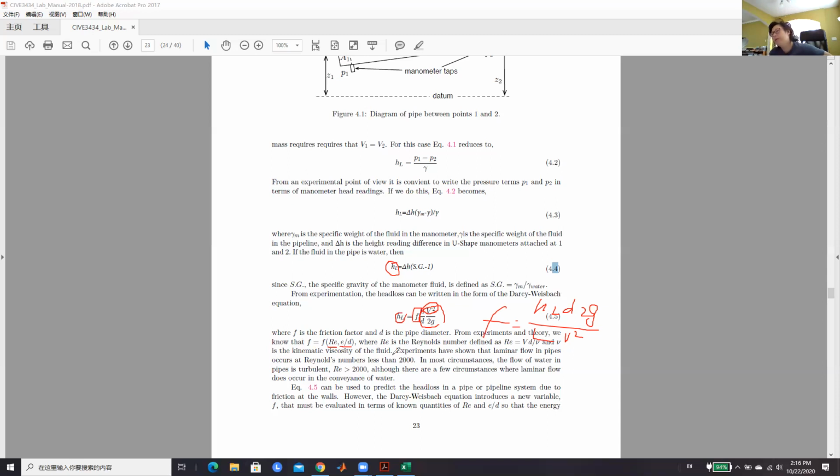Okay, and since it's room temperature, you can just use probably 70 or 75 Fahrenheit. Okay, use that number, because the kinematic viscosity depends on the temperature. Let's say just use 70. Okay, that's one part I need to check in your lab report, if you find the right number.